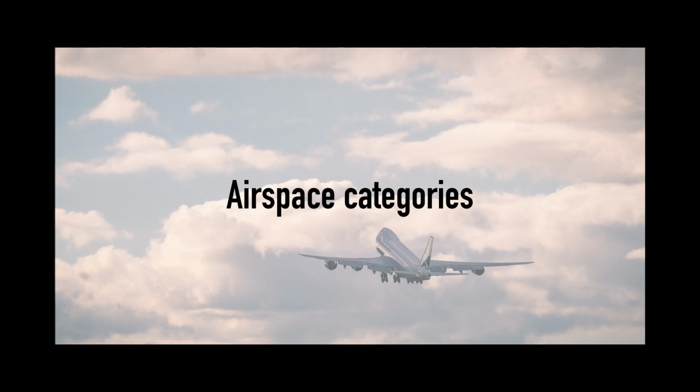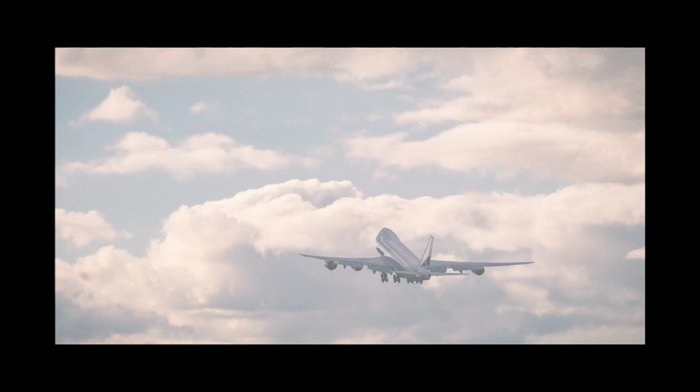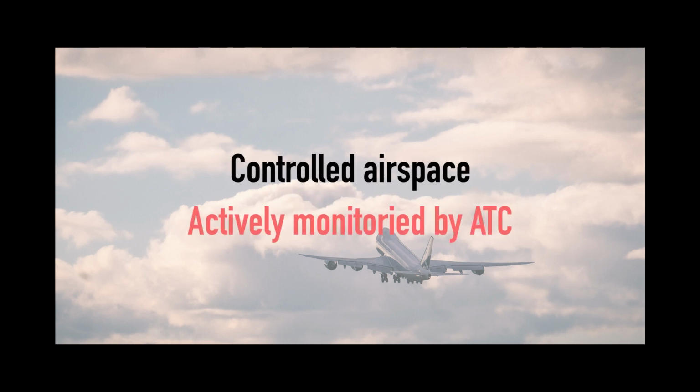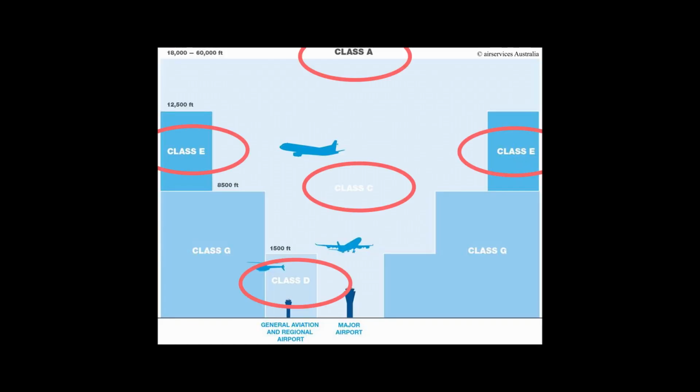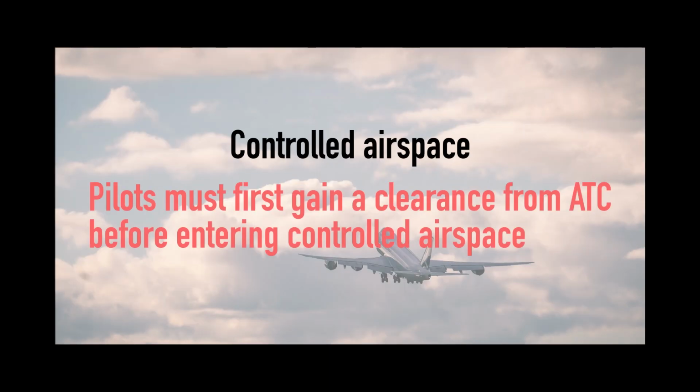There are two kinds of airspace in civil aviation: controlled airspace and uncontrolled airspace. Controlled airspace is actively monitored by ATC and is broken up into different classes, like Class A, C, D, and E. Different rules will apply to different classes, like how far and how high you can fly. Aircraft pilots must first gain a clearance from ATC to enter controlled airspace.